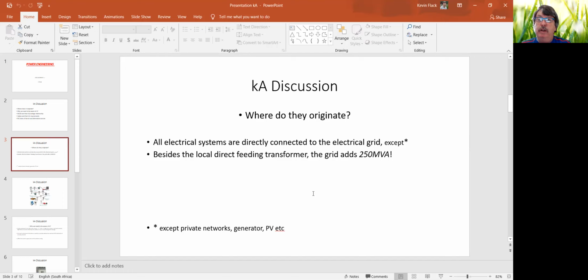Older township areas might have a little transformer, might be in a little transformer house, may not be obvious in some areas. If we have a look at townhouse complexes, there could be a little power transformer area, grid network connected outside the main feed coming into that place. Generally speaking, the houses are more compact in those areas, and so the risk is that you need a slightly higher kA than what you might have on the more traditional type township layouts where there are large distances in between.